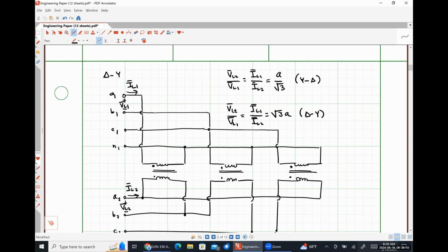So one of them isn't really behaving like ground. We don't have to have a ground in an AC system. We usually do tie things back to an earth ground. But a single-phase AC system contains a hot wire and a neutral wire, and the neutral wire is what we commonly associate with the negative polarity terminal of our voltages. All an AC voltage means is that the potential between those two wires is constantly changing in time. It doesn't matter what the individual potential on either wire is; we just know that the difference between them is exactly some amount.